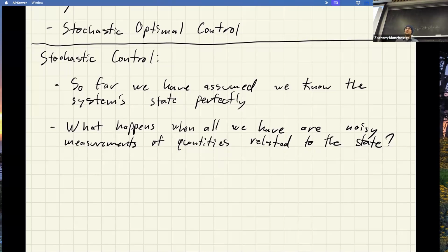The other big gotcha with mocap systems: they have delay. If you're doing something like flying a drone around, has anyone ever tried to close a feedback loop on a drone in a mocap studio? What happened? Yeah, exactly. Typically they have about 20 milliseconds of delay, give or take, and that delay is enough to completely hose your control loop, and you cannot stabilize a hover on a drone in a mocap room without doing fancier things. So even when you think it's a pretty benign setup, that's the best case, right? It's super fine accuracy, but between the delays and the fact that you don't get velocities, you just can't do it. So you always have to think about this stuff to some degree.